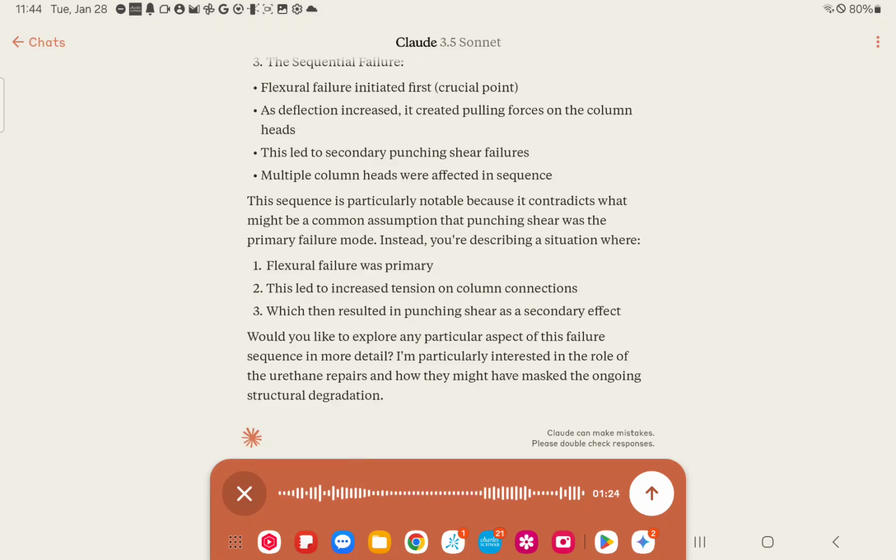And now you still load the deck. You do get initially some bond strength with the epoxy from one side, bridging one side to the next. But remember, the PSI of our concrete is only 4,000. So the tensile strength based on ACI is that we're only going to get 400 pounds of ultimate bond strength.